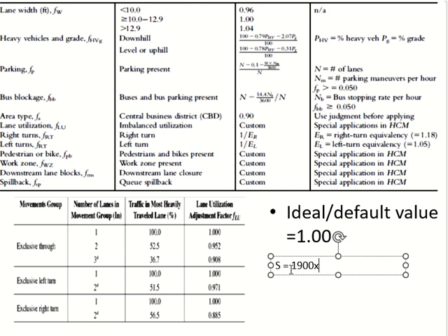Can I use the average? Average for what? No. We will not use average. If you start taking average, you can see how many factors we have, so it will create a big change. We cannot use average. But the point I was making about the base value: you can have a different base value for each lane group if you have observed it. Clear? Okay, the first factor is for lane width.